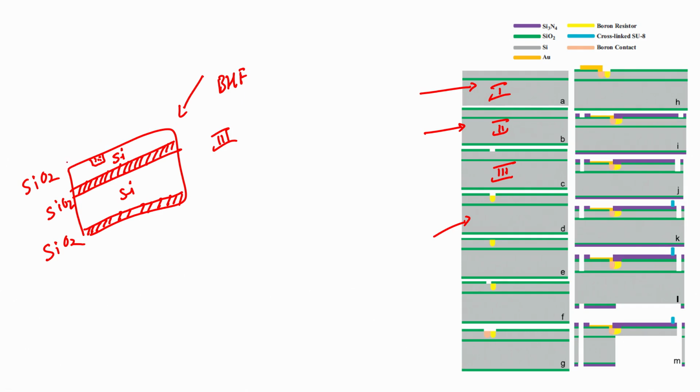So, you have to regrow silicon dioxide like this, and that is why you can see this particular step, this is 4, this is 5. In this 5th step you can see silicon dioxide is again grown after diffusing, and then you again create a window, such that this window would be overlapping a part of the boron diffusion. You are creating the window for diffusing boron with a higher concentration so that the conductivity is high, and that is used for the boron contact, and this is what you have done in step number 7, right.